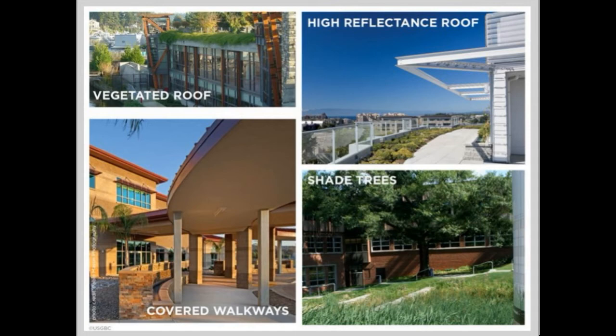This credit is eligible for exemplary performance for all options. I recommend understanding each and memorizing their thresholds. Here are the exemplary performance opportunities for each option. Option 1. Install SR-compliant materials or open grid paving, or provide shading within 10 years for at least 95% of non-roof impervious surfaces. Option 2. Install a vegetated roof system for at least 95% of the project's roof area, excluding any mechanical equipment, photovoltaic panels, and skylights.